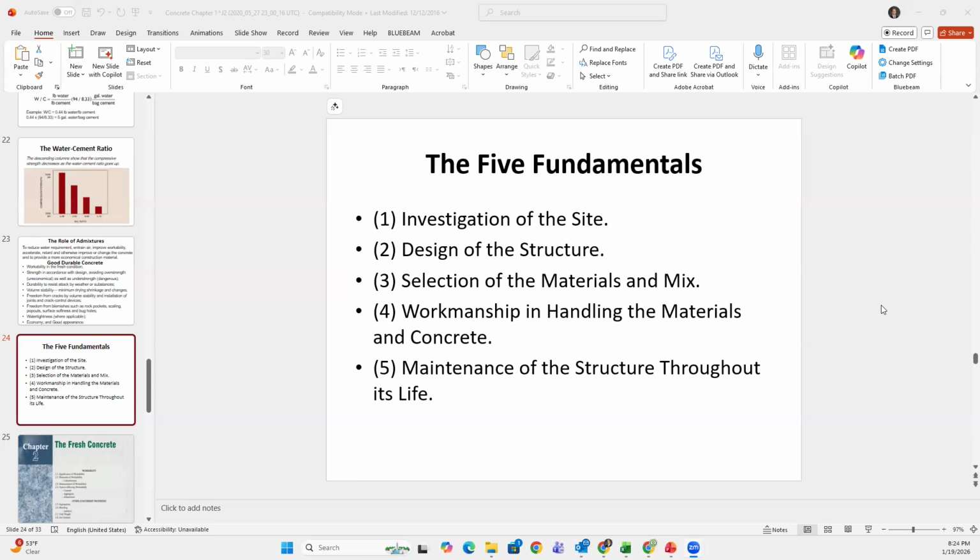Is that concrete good anymore? No. So that's why, for the timing of a concrete pour, contractors normally do it early in the morning, especially if you have a big job, you line up your concrete deliveries one right after each other.